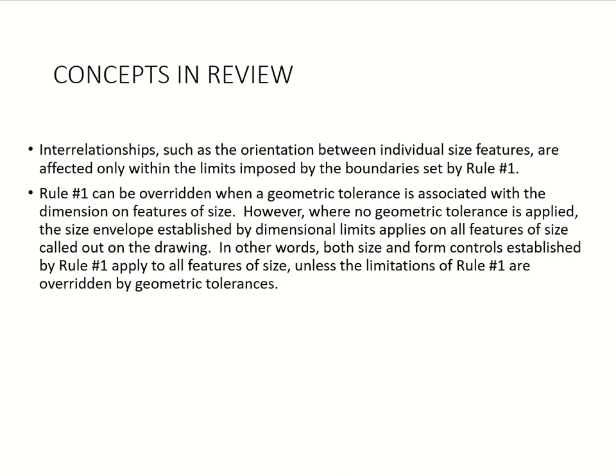Right now, just concentrate on the tolerance zone and tolerance limits, always attached to your dimensions. If you cannot find the tolerance limit with the dimension in your diagram, it has to be in the title block. Follow them. Upper limit, lower limit, very important. Everything that you do has to be within that limit, regardless of perfect feature or variations in form, because they are acceptable as long as they are in that range of your tolerance. That's all you need to know for the first part.